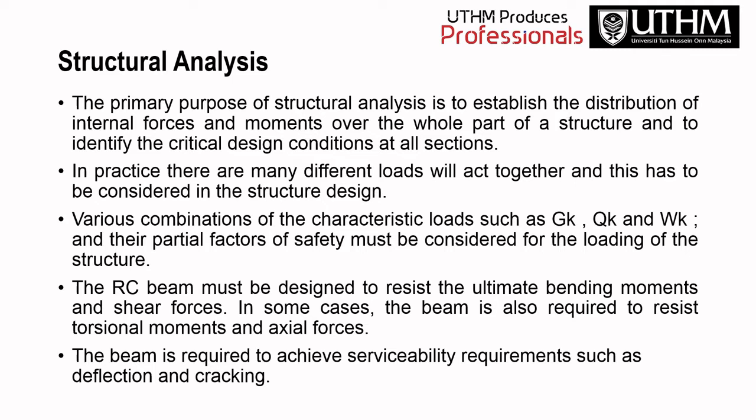So the primary purpose of structural analysis is to establish the distribution of internal forces and moments over the whole part of structure to identify the critical design condition at all sections. So in practice, there are many different loads acting together, and this has to be considered in the structural design. So various combinations of the characteristic loads such as GK, QK, and WK, the wind load, and their partial factor of safety must be considered for the loading of the structure. So we need to use the partial factor of safety to make sure the structure is safe for the design,